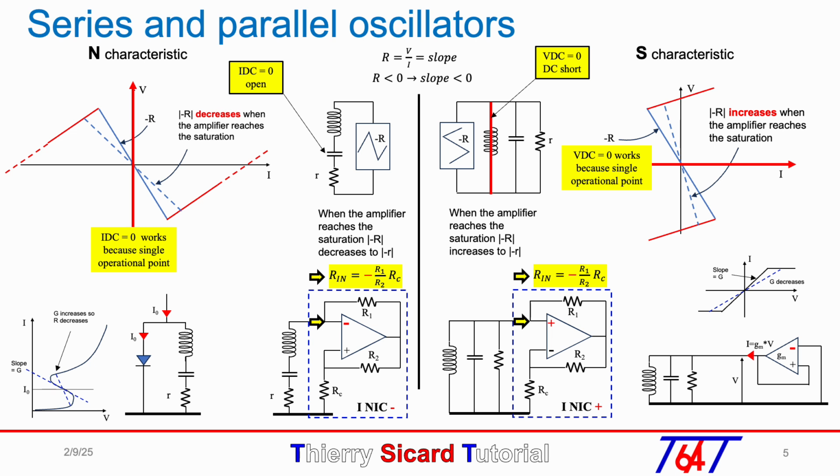So if we connect a parallel RLC across the transconductance output, the resonance circuit will start oscillating with a low conductance, allowing for an increasing amplitude until saturation, which allows for a lower conductance exactly equal to the RLC conductance.